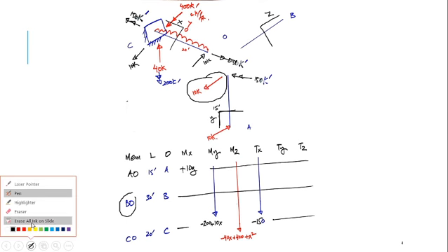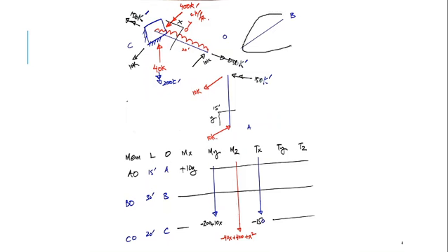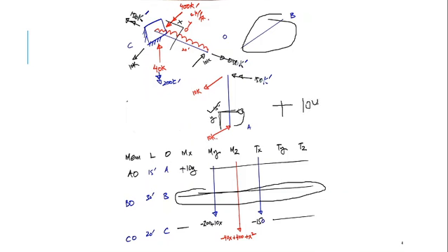Okay, finally, starting from section BO, there is no activity here, so all the values would be 0 as shown here. From the AO perspective, you can see the origin is A and you know this is Y. You have to find all the moments here. This section has been named Y. You know this is forming an anti-clockwise moment, 10Y, so this would be balanced by a clockwise 10Y. This is in Z direction and this member is in Y, so this should be a clockwise moment about X, so it would come under MX.